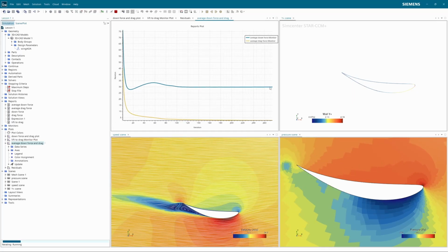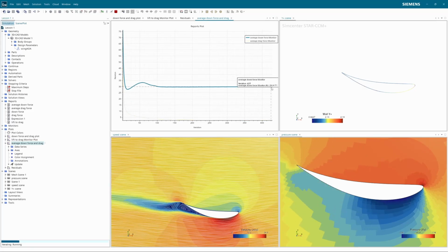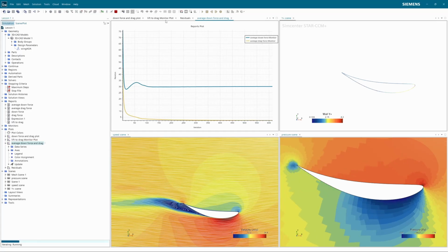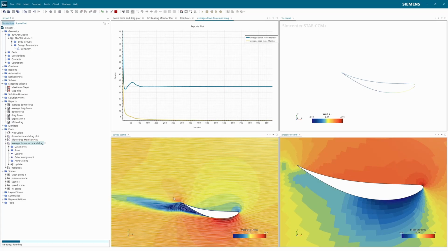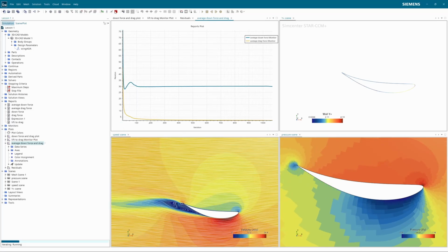So as you can see, these values are now smooth. It doesn't change the actual values that are happening, but this creates a much more readable value. You don't have to do any calculations afterwards. But you should still take into account that the values are fluctuating, since that is actually a bit worse than if they were just constant. But I mean, vortex shedding is sometimes unavoidable, and it's just the way it is. So it's still quite useful to have these averaged values.